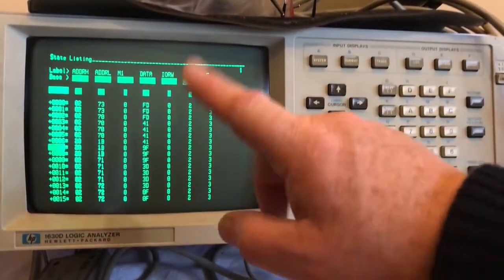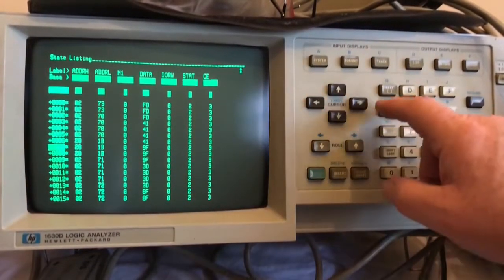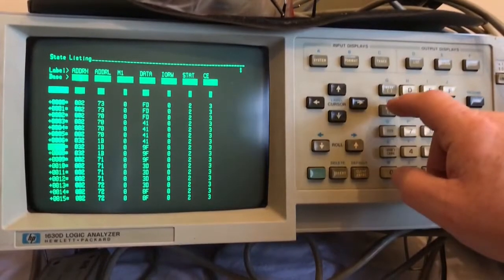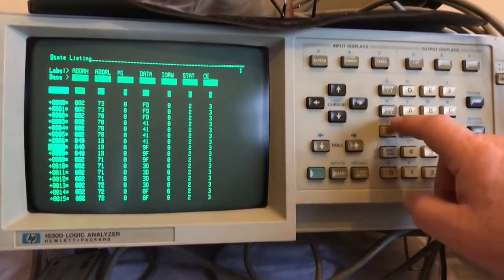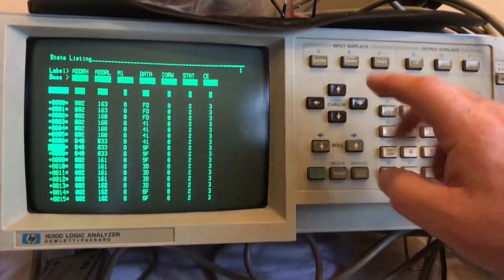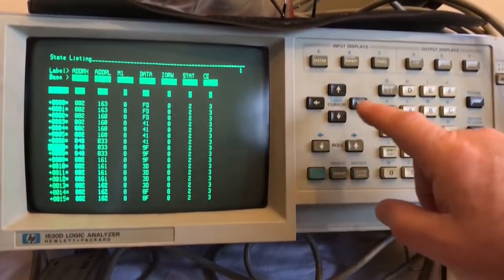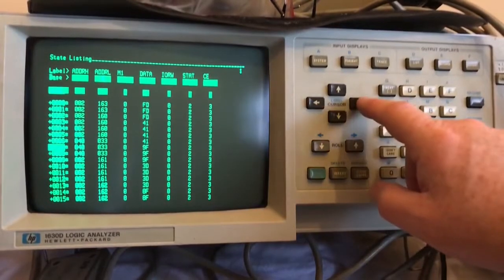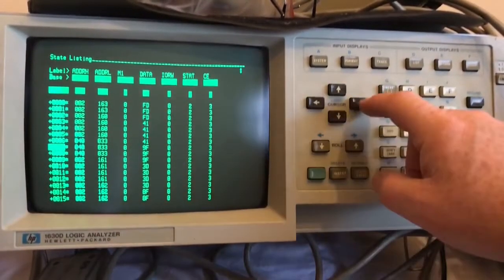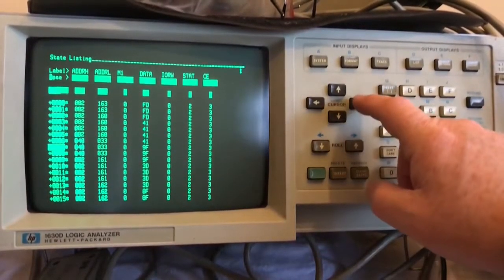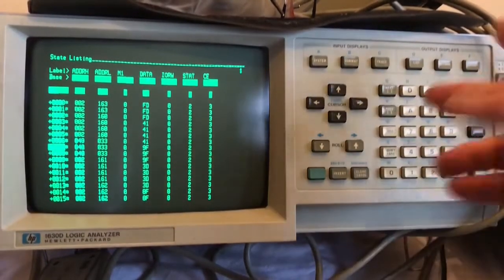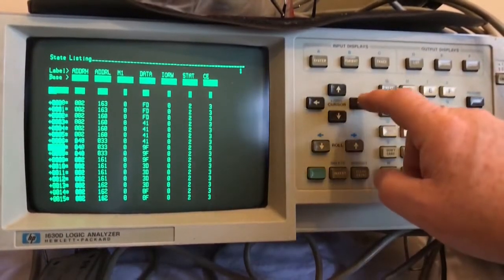Now what I'm going to do is change the address high to be octal, and we're going to change the address low to be octal as well, because by doing it in 2 halves it gives us the split octal that the H8 uses. The M1 is a hex line, but you just see 1 digit anyway, so it doesn't matter. The data I'm going to see in hex, because I recognise things in hex quite quickly.